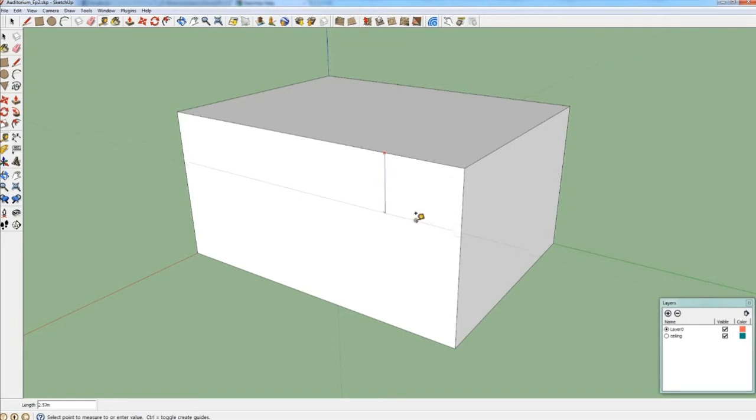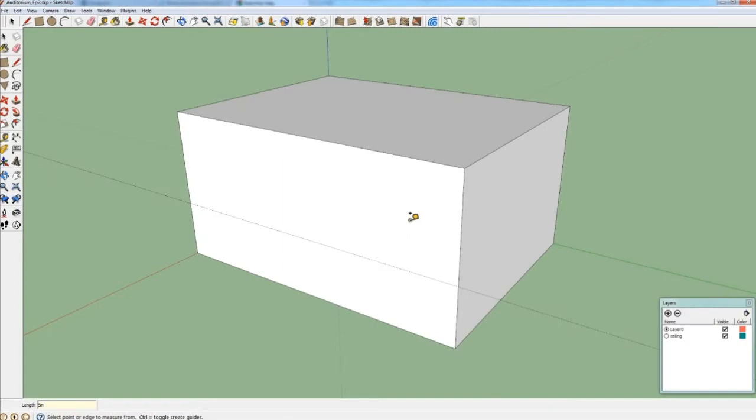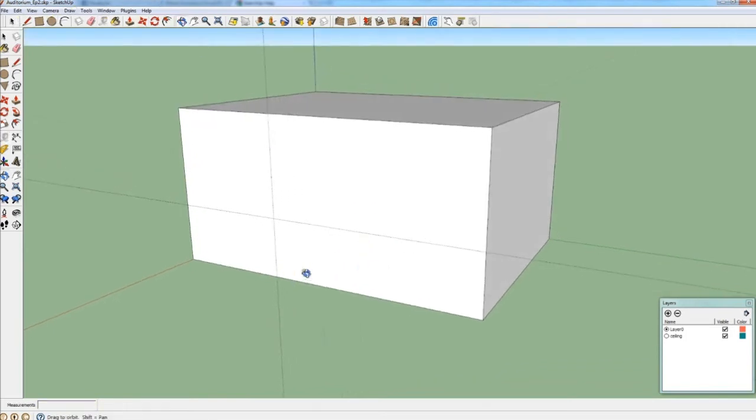We should be careful to stay towards the blue axis, and before clicking again I just finish the geometry by typing 5m, so this is 5 meters away from this edge, and then I need another one parallel to the vertical edge, 5.5 meters away. So roughly now I have defined the region where my stairs should be.